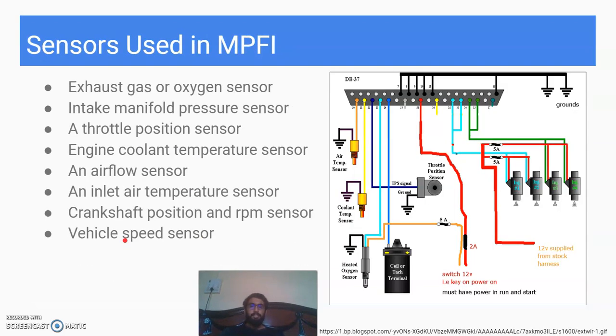So what really happens in the case of MPFI is that when the ignition switch is switched on, the electric supply from the battery is passed to all the sensors, the ECU, the fuel pump and the starter motor. And when the engine starts cranking, the starting motor signal sensor is activated and sends a signal to the ECU. Now fuel to the engine is increased to start the engine easier. The throttle position sensor is activated by the ECU and the throttle valve is opened according to the acceleration and the engine temperature.